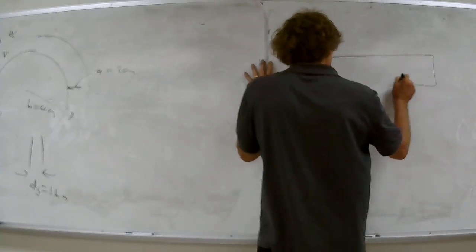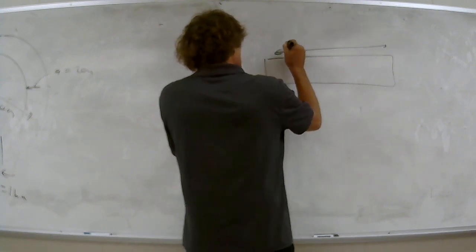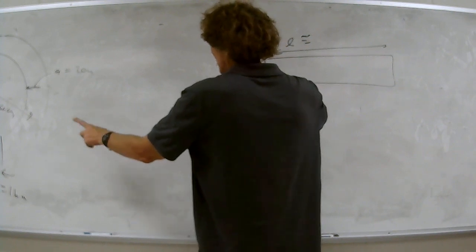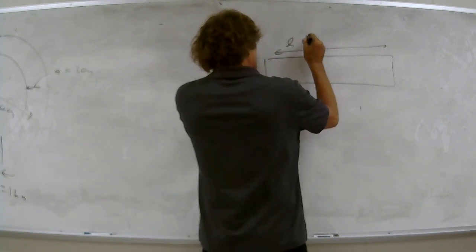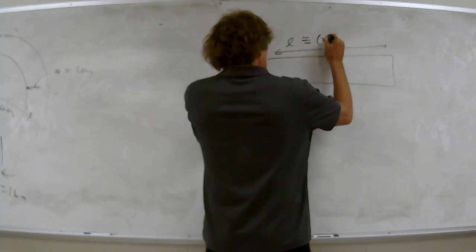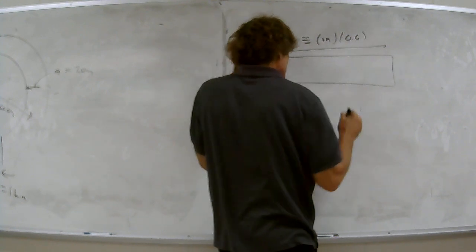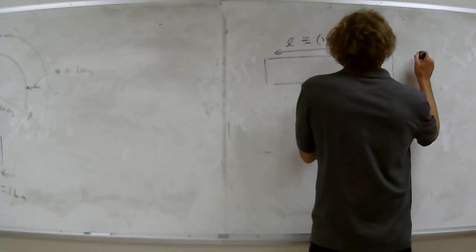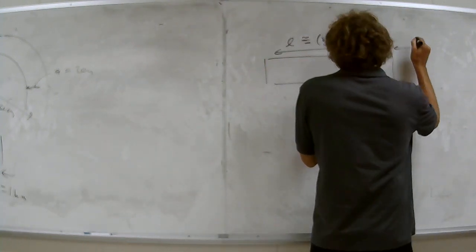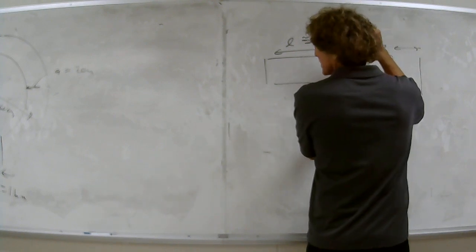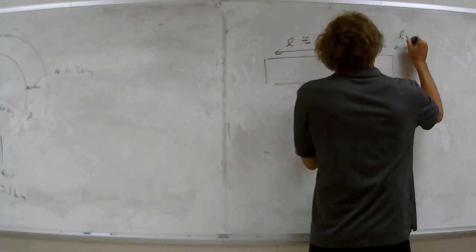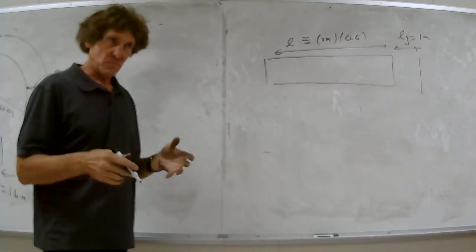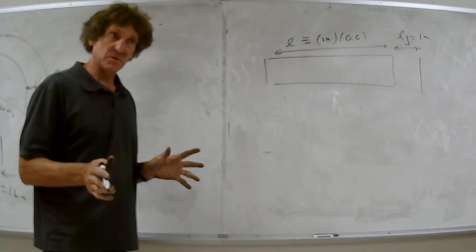I have something with a length that's approximately equal to, the total length is going to be 2 pi times 60 centimeters. Well, this is about equal to 2 pi times 0.6 meters. You with me? And then you got this little gap here you have to deal with. So this gap itself is 1 millimeter. The gap length is 1 millimeter. Now, I'm going to draw the equivalent reluctance model of this in series. You with me?